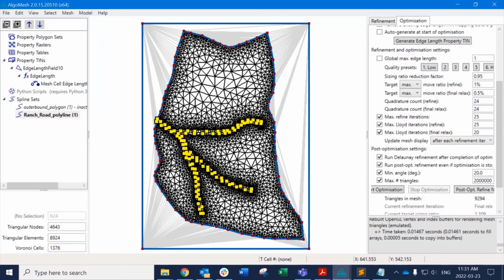And then the other thing about model performance, again, is accuracy. Accuracy of the simulation also has a bearing on how well the model will run. So having a more accurate model is also going to generally lead to easier simulation convergence. I don't have any benchmarks or tests that we can discuss here, but the general rule of thumb is that a higher quality mesh is going to provide a more accurate flow solution, and it's also going to result in lower runtimes. So in both cases, model performance should increase.